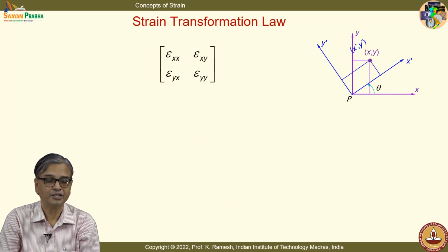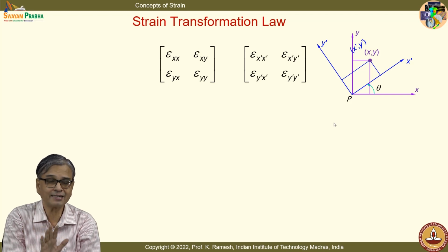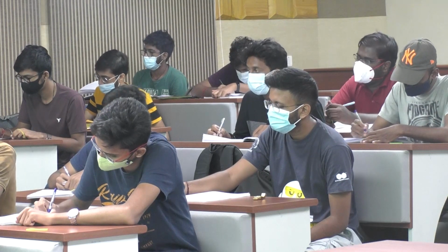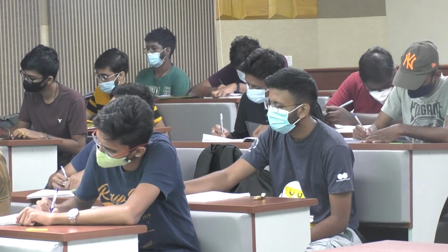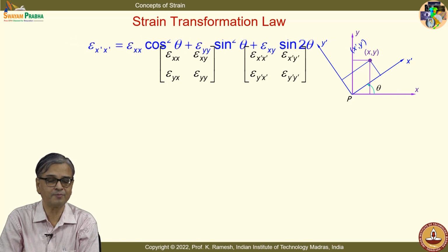And you have to write that rotation matrix. If you know how to determine x prime y prime from xy, and you write that rotation matrix correctly, like you have written down the stress transformation law, can you write the strain transformation law? You know how to write it from indicial notation. You can also write it from epsilon x prime. I have the diagram given. From that you can easily write the rotation matrix. You will have an identical image because all tensors transform in a similar manner.